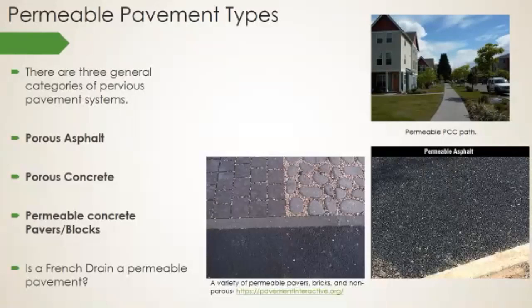Not any of these systems are really applicable to heavy duty traffic with trucks and a steady, constant traffic of vehicles of different sizes, because of the lower weight capacity or strength of these materials. But they are well suited for, say, a residential street, where we've just got residential car and small vehicle traffic, footpaths, bike paths, parking lots, things of that nature. But highways, it's probably not applicable.